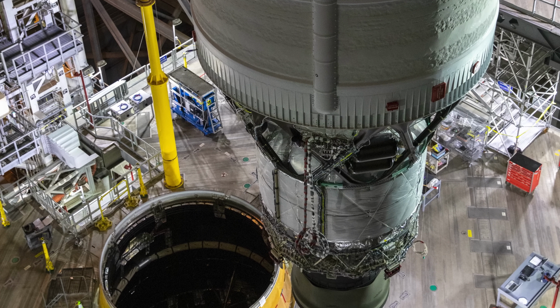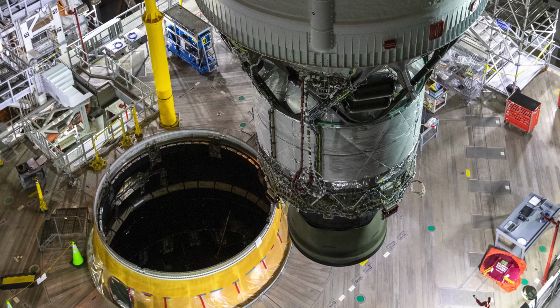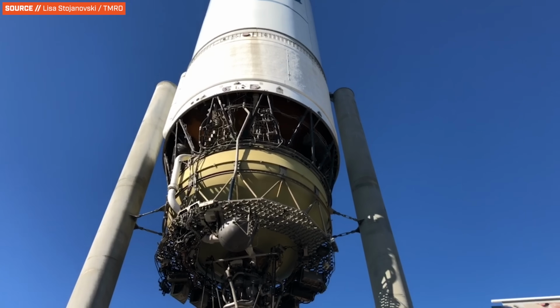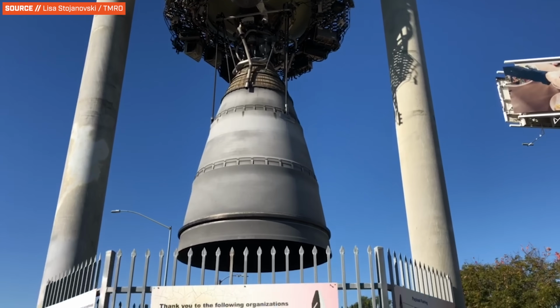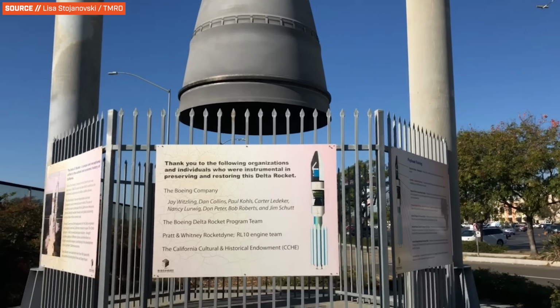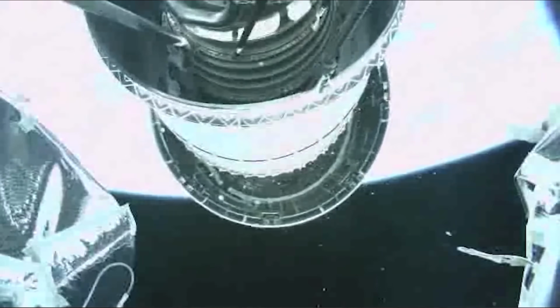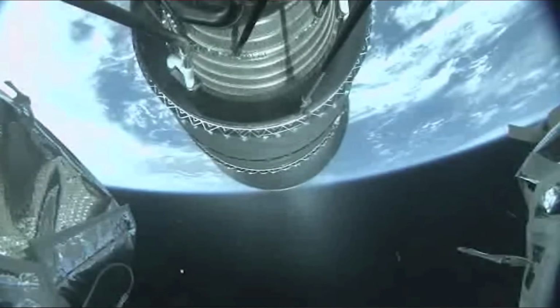These engines can reach ludicrous levels of efficiency. In fact, the RL-10B2, which utilizes the expander cycle with hydrolox propellant, reaches 462 seconds of specific impulse. This is about the upper limits of what's even possible for chemical rocket engines.